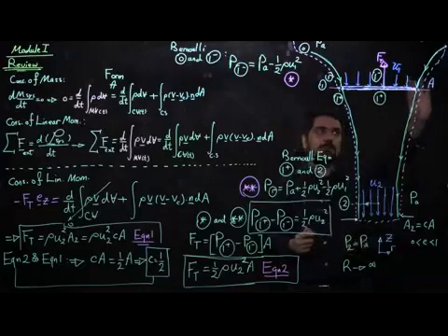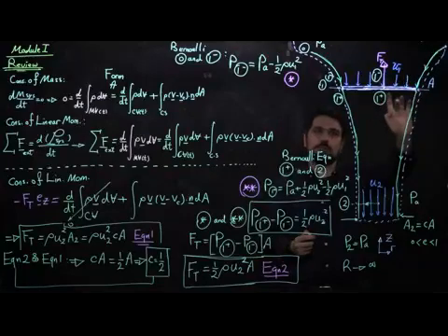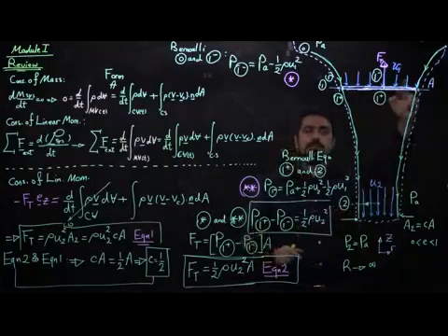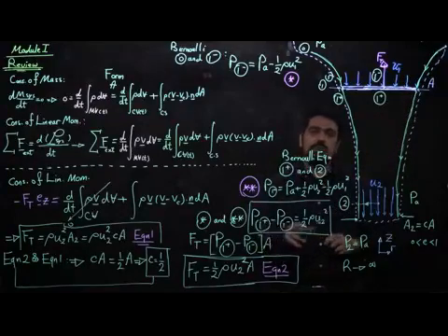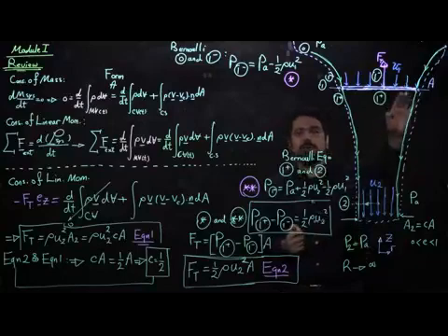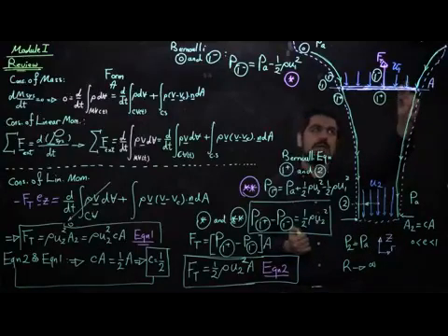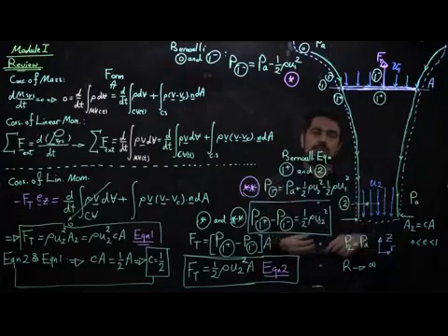One thing that is very important here is that velocity remains continuous as it passes through this blade. But pressure, as you have seen, sees quite a bit of increase. This increase in pressure, if you want to think about it physically, happens because you are doing some work and adding energy. So as the flow passes through this blade at a constant velocity, the work and energy that you are doing on the fluid elements lead to an increase in the pressure.